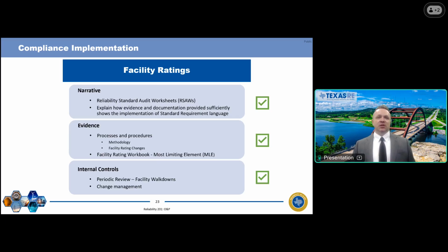Your methodology should be updated, and your facility rating changes to your workbooks should be reviewed and peer reviewed. The intent of this workbook is to identify your most limiting element, and that most limiting element is being communicated to your transmission planners, your transmission operators, and your planning coordinators. And in ERCOT, these are determining your security operating limits and your IROLs as well.